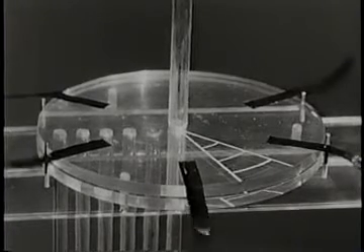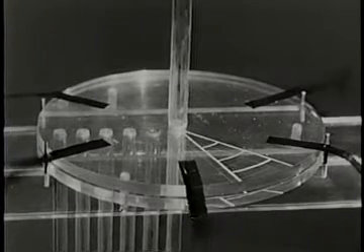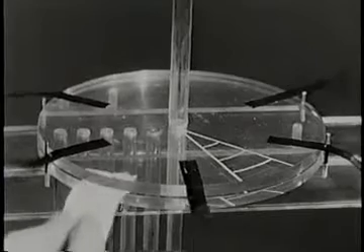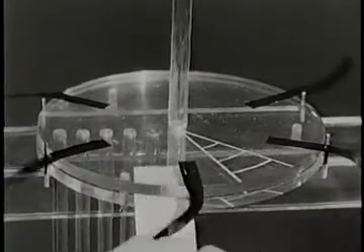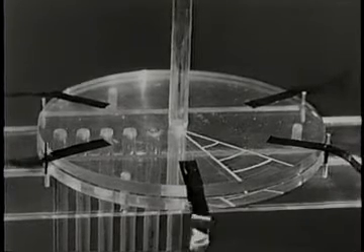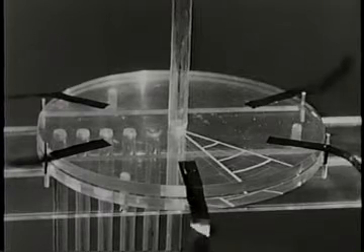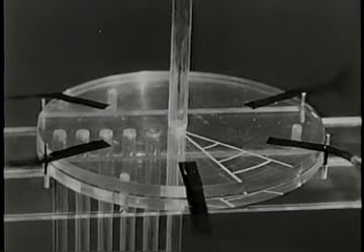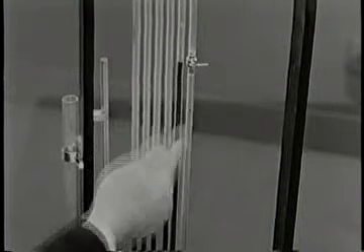Actually, the viscous forces in the narrow gap are by no means negligible. But in this particular experiment, the mass acceleration forces are generally larger than the viscous forces, and so they govern the shape of the pressure distribution. The subatmospheric pressure over most of the area explains why the disk is lifted.